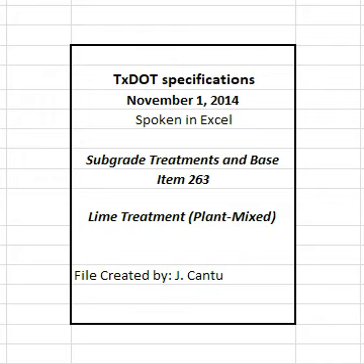Asphalt used solely for curing will not be paid for directly but will be subsidiary to this item. Asphalt placed for curing and priming will be paid for under Item 310, Prime Coat. Removal and disposal of existing asphalt concrete pavement will be paid for in accordance with pertinent items or Article 4.4, Changes in the Work. 6.1 Thickness measurement for cubic yard in final position and square yard payment adjustment. Before final acceptance, the engineer will select the locations of tests within each unit and measure the treated base depths in accordance with TxDOT 140E.